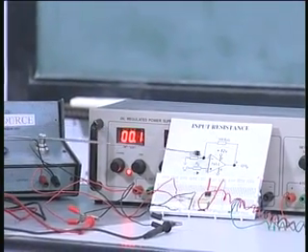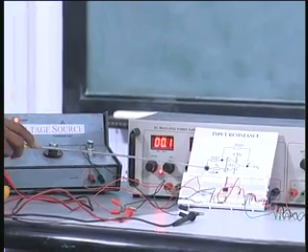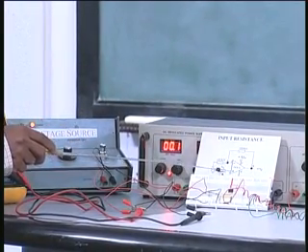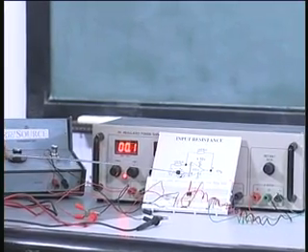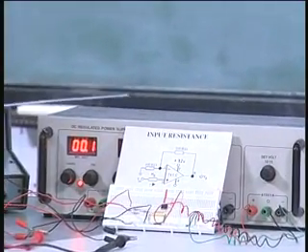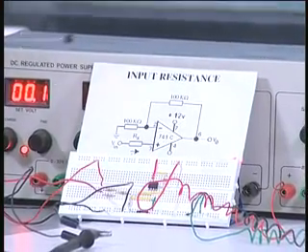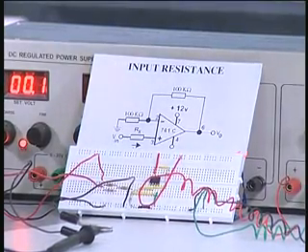They are equal value, and I give the input voltage here from the millivolt source, and I measure the output voltage, and then I introduce the Rx here of an appropriate value, so that the output is up near about half the value. If that happens, then Rx should be equal to R in. That is the principle.